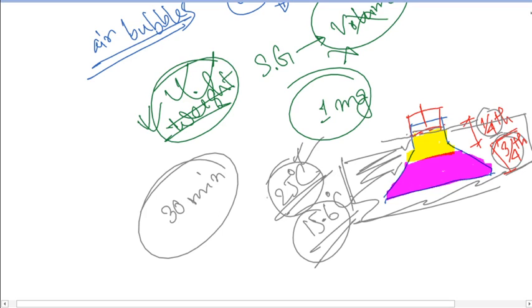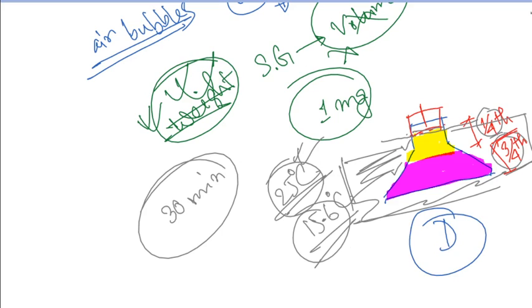Then you will take the weight again. This weight you are taking will be designated as T, and that indicates the pycnometer plus partially filled water and partially filled semi-solid bituminous material.